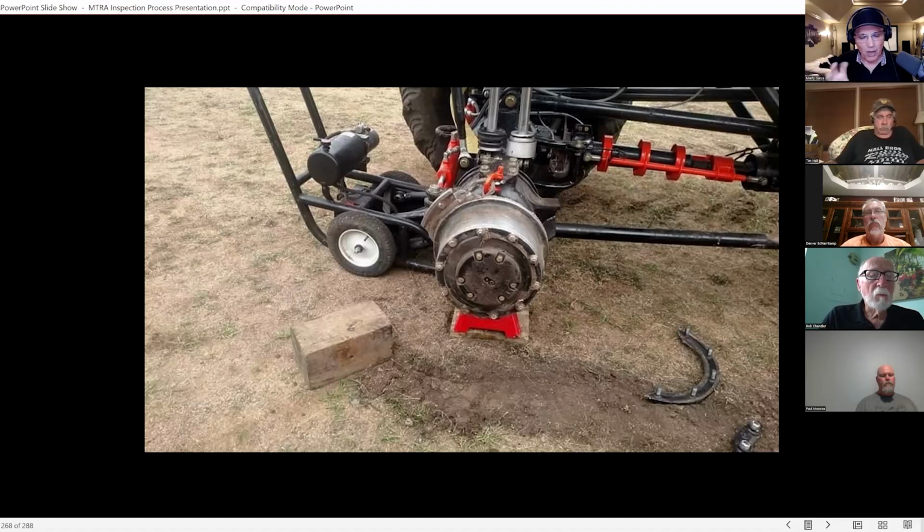That's why the good seasoned techs, after they're tired up and the truck moves from the pit area to the floor, will go back and recheck the lug nuts, just in case the wheel wasn't perfectly centered and it moved and now it's loose. The wheel will kind of center up for a minute until you go out and run hard.